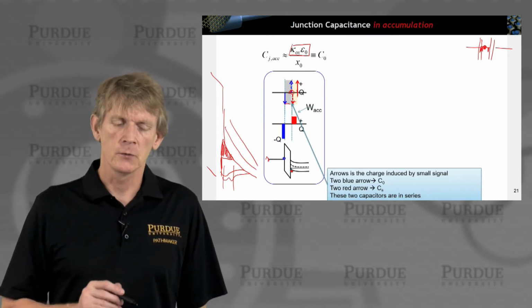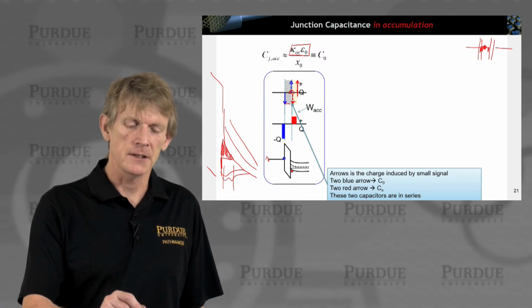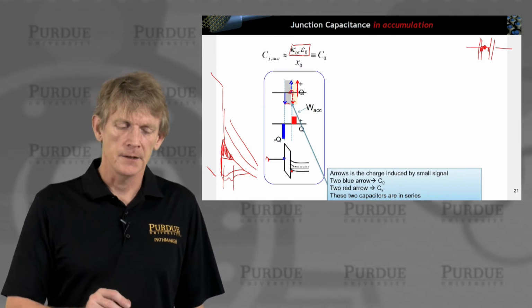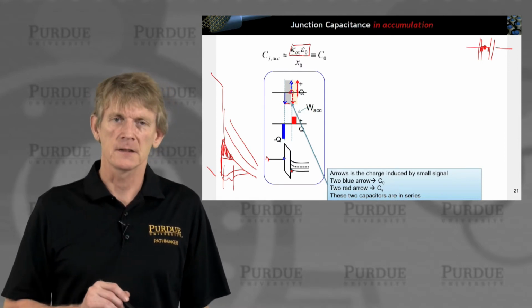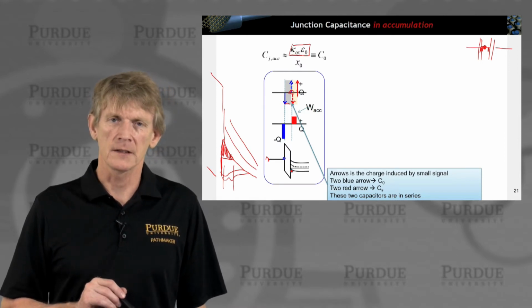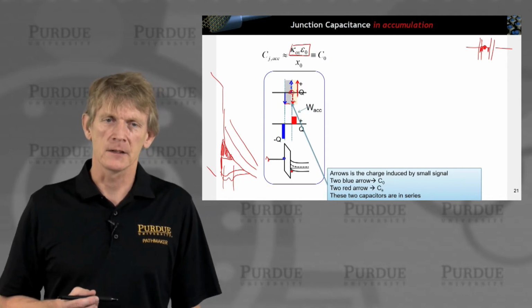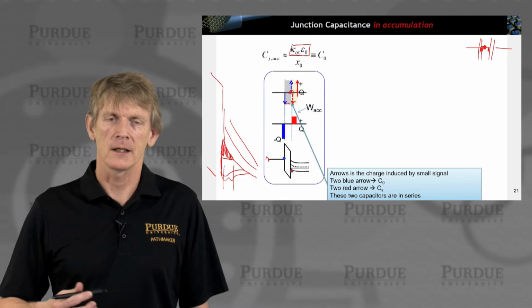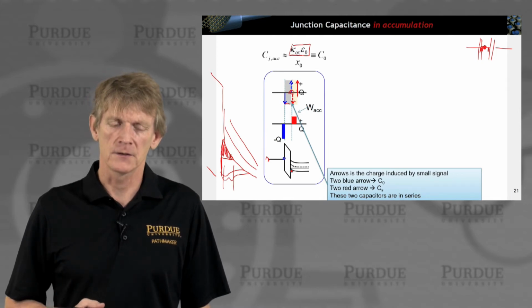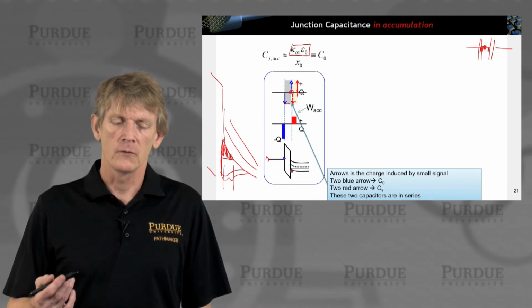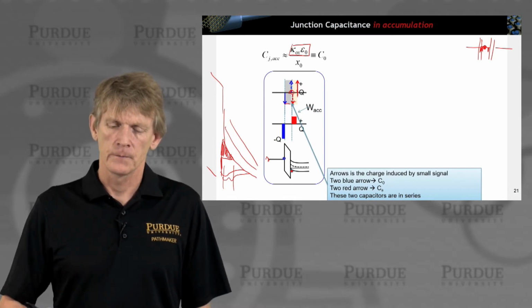You have some positive charge that sits at the semiconductor tail end, and some negative charge that sits at the metal oxide interface. In between, you have two delta functions that cancel each other, but it allows you to calculate the series capacitance in the system, where now the fields drop off over different dielectric constants.